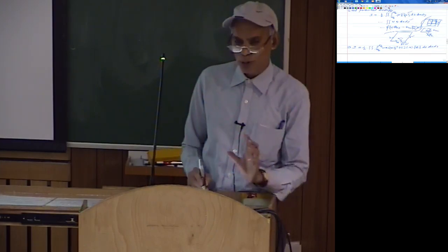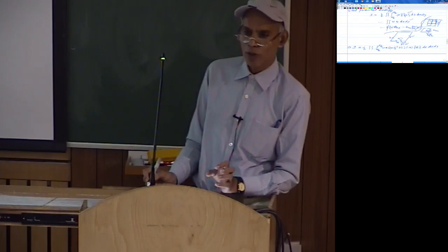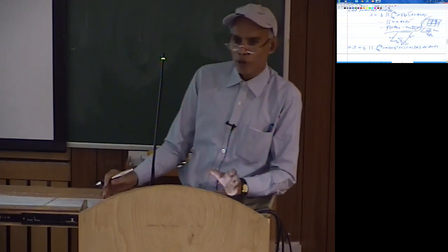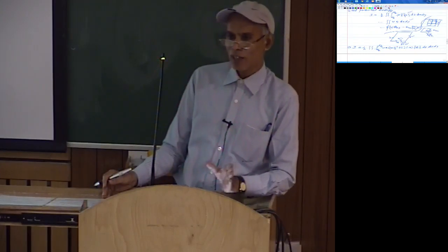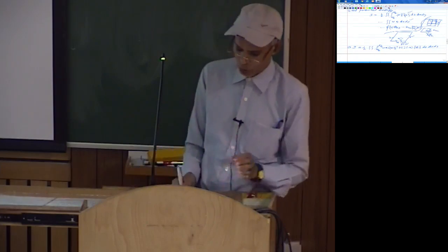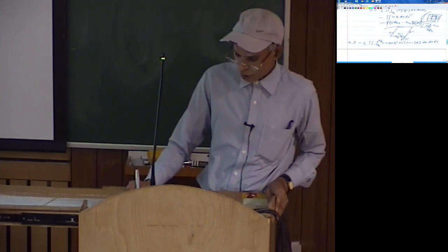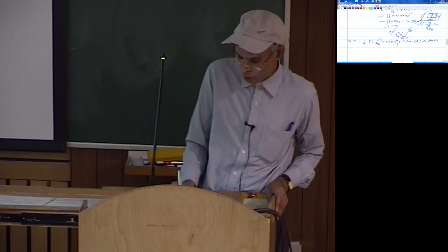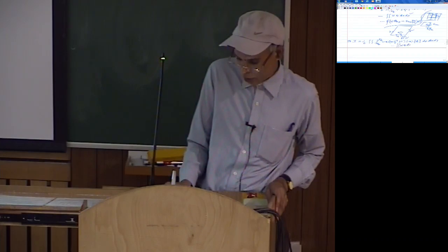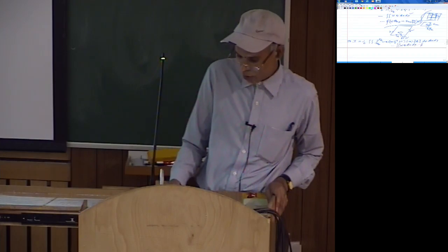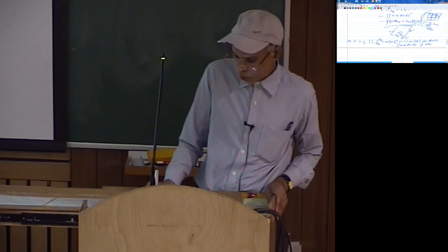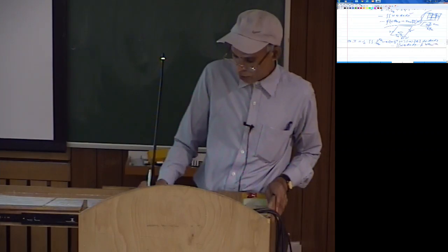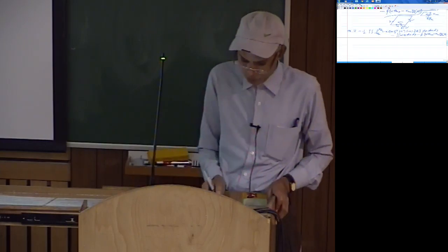So here I have used a couple of steps: sigma equal to C into epsilon, and epsilon is minus z into kappa. If you substitute that, this is what you will get, and the other two terms of course remain the same, that is the integral of w q dx dy and minus the integral of w q n z minus mn into del w by del n ds. These remain the same.